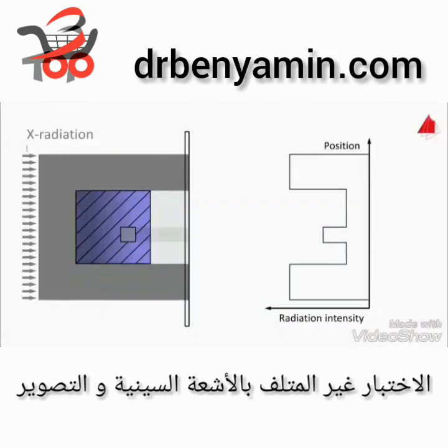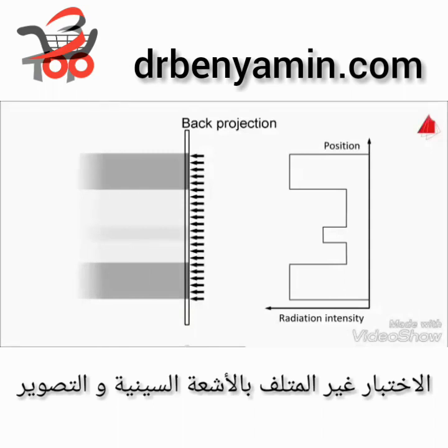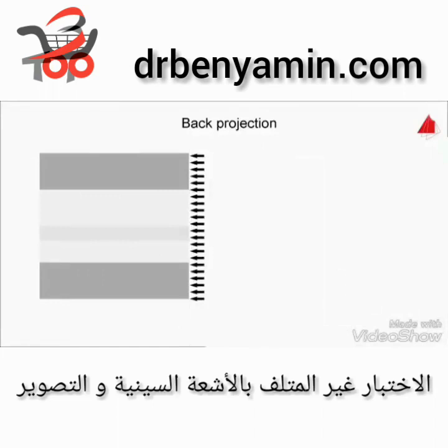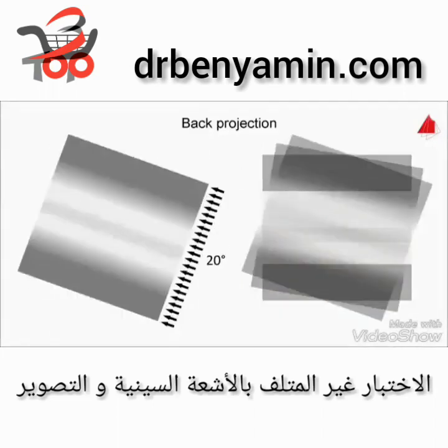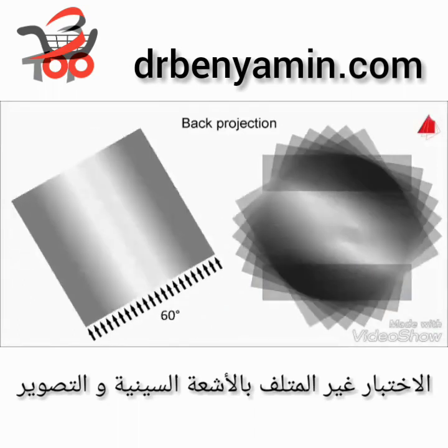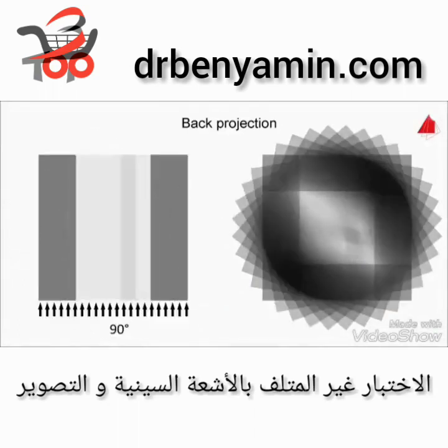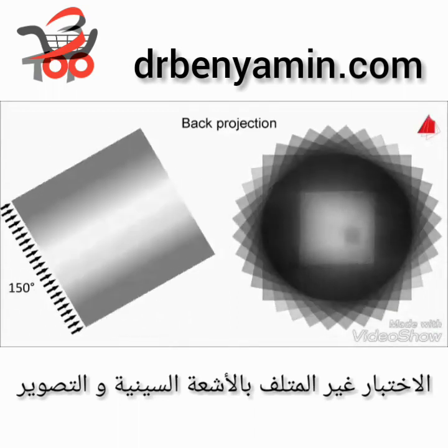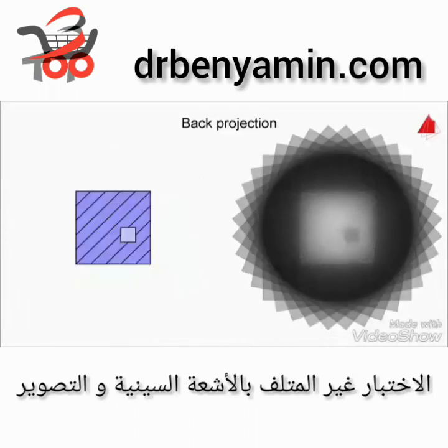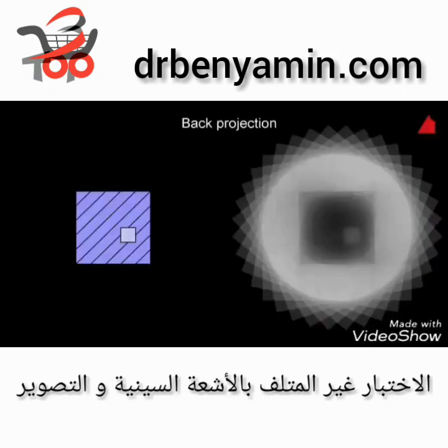After having taken all X-ray images, the distribution of the transmitted X radiation is projected back into the sectional plane. This process is repeated for each X-ray image, and the distributions are superimposed. With each superposition, the quality of the model increases. Displayed as a positive image, the back-projected plane looks like this. Much better results can be achieved with appropriate filter methods and with even more images.